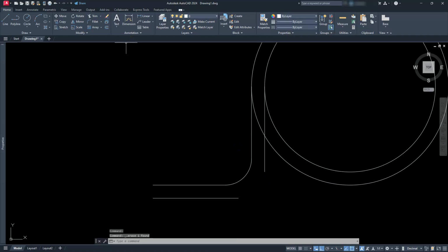And the proper way of doing that is either to figure out the fillet, or you can use the offset command. And remember, the offset distance is going to be 1. And then when I offset that, that gives me that more smooth contour shape that I was looking for, right? So that's one of those little drafting secrets of how you can make your drawing look a lot better there. Let me go ahead and delete that.